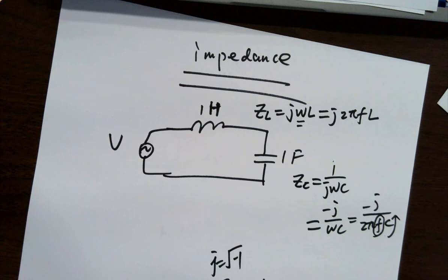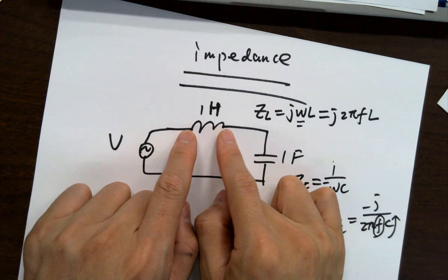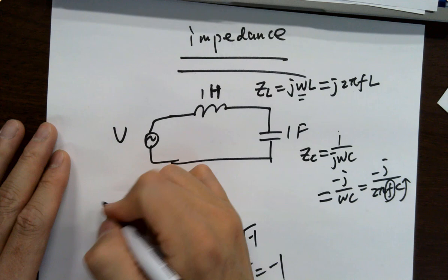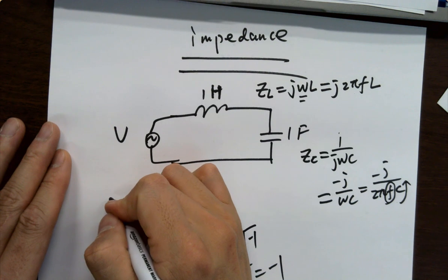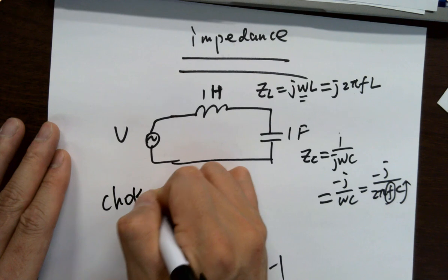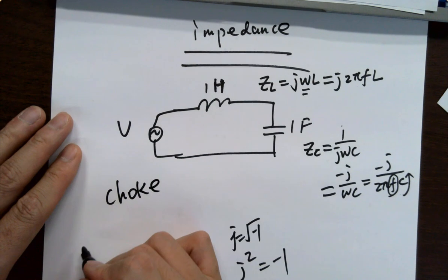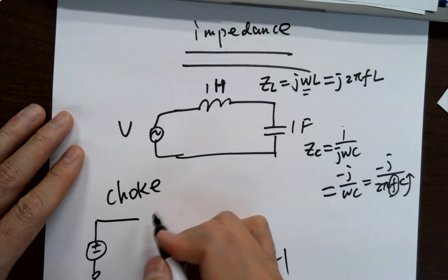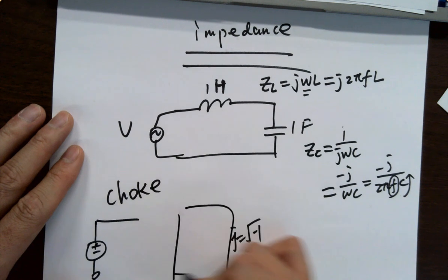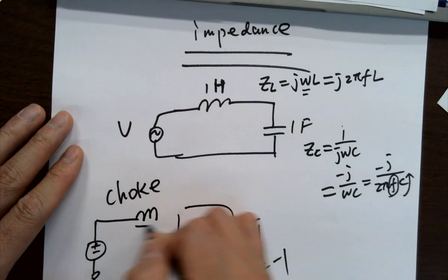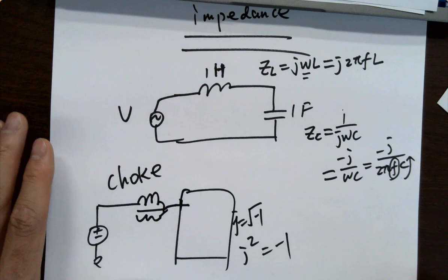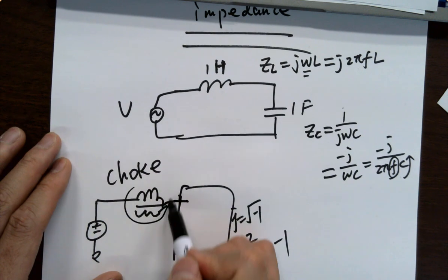Whenever you get noise in the ground line or power line, you put an inductor in there, and it's going to block high frequency noise to make your DC power supply more stable. That's called an inductive choke. So what you do is, for example, here's the source, and you want to supply this voltage to something, your load. And you can have a couple of inductors there. It's a really interesting circuit, since I used it for one of the products I sold to a company. And you have this inductor in the middle.